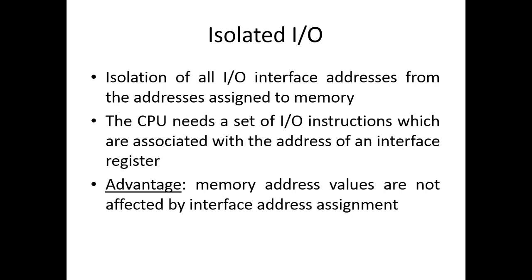required I/O operation. In case of a memory reference instruction, the CPU places a memory address on the address bus after completing the fetch and decode phases for that particular instruction, and then activates the memory read or memory write line, again depending on the type of the needed operation.